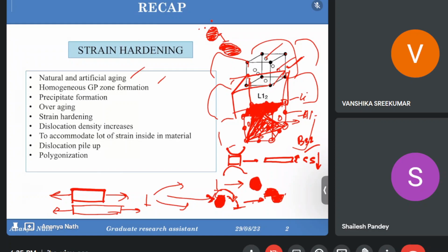So what happens is the barrier in the movement of the dislocation is happening because of themselves only. This is how we really do the hardening in the non-heat treatable alloys, by forming a new set of dislocations. Previously the dislocations were moving so fast that the solute atoms couldn't catch up with them unless we increased the strain rate. But now we have played a little bit differently.